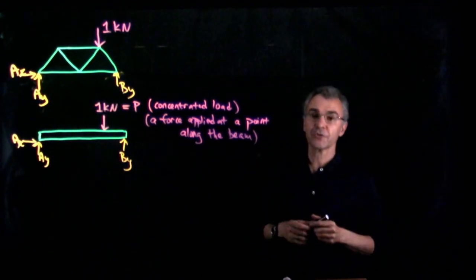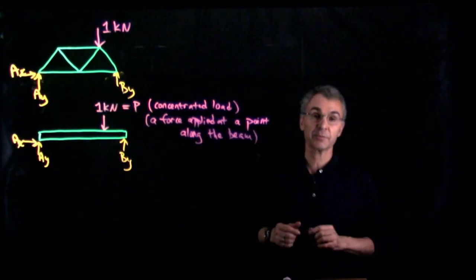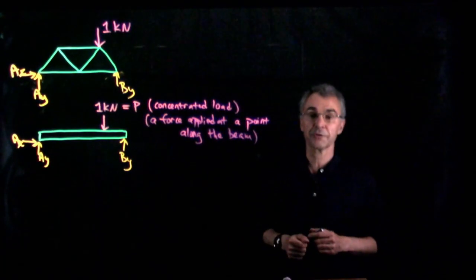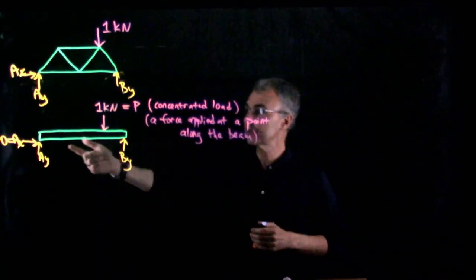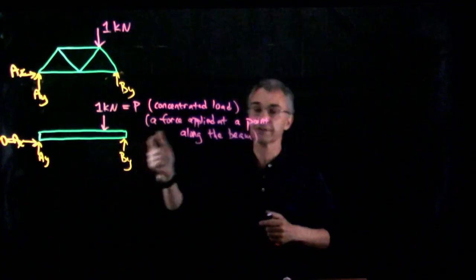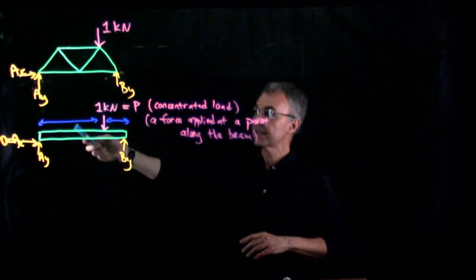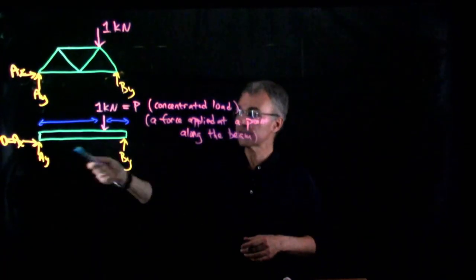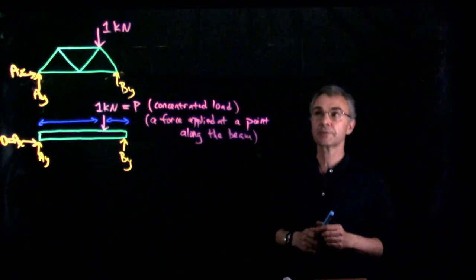And typically one of the first things we do with a beam is to solve for these support forces. Any load applied to a beam in our simplified treatment of beams in this course will be vertical. So this horizontal support force will always be 0 in the beams that we discuss. But in general, for a simply supported object, there could be a horizontal force here, a vertical force here, and a vertical force here. So given the value of this load or other load forces and the relevant dimensions, so we know where along the beam each load acts, we could solve for these support forces, which in this case are called AX, AY, and BY, using the familiar rules of statics.